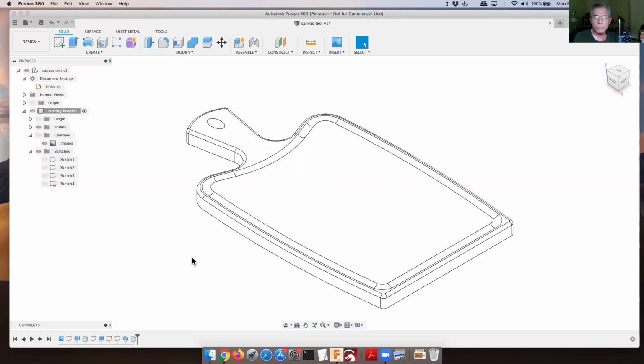Yes, Tim. You drew the profile 3/8 of an inch in from that one edge. And you said it didn't matter if you were lined up with the original offset line. At this point, could you just say that instead of 3/8 of an inch in, you were 1 inch in, even though you're completely outside of the original line, and would it follow it? It would. The only thing we've got to worry about is what happens here, because if we go in an inch, this radius is going to go negative.